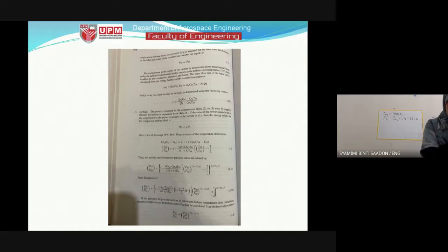Then 0.5, but in order to calculate 0.5, we have to calculate the fuel to air ratio first. So using the same equation, this one, for fuel to air ratio: CP 1005, or 1.005, TO4 1300, TO3 397 just now, QR, the fuel heating value, 45,000.